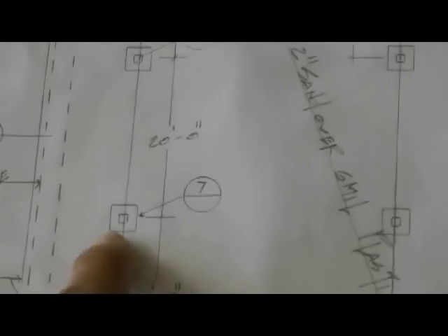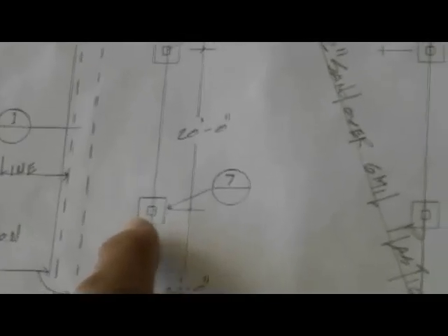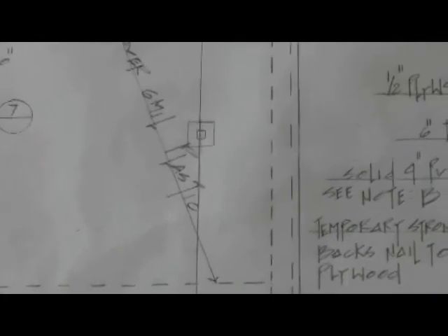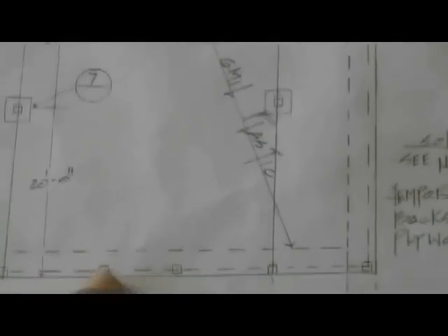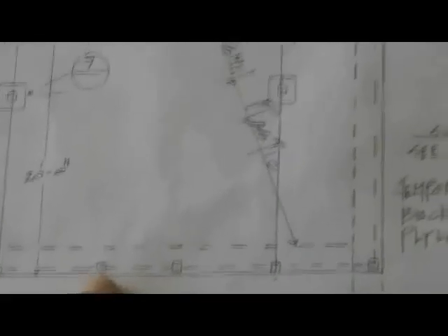So these posts will hold their weight, but they need to seam weld those things together and then cut them to the height that's necessary. Now, from the top of the ridge, I'm going to show you that in a minute on another page. From the top of the ridge of this church building, it's 20 feet all the way to the top of grade. So that means that the walls, using a 4/12 pitch roof, are 10 feet 6 high. I'm going to show you some information on the next page. We have to maintain these pad footings in place where they're calculated to be.